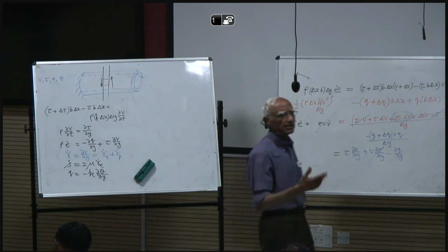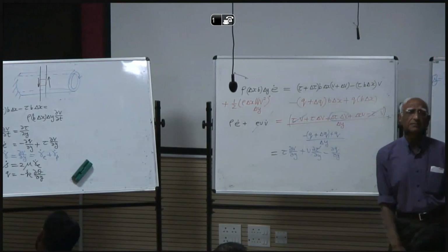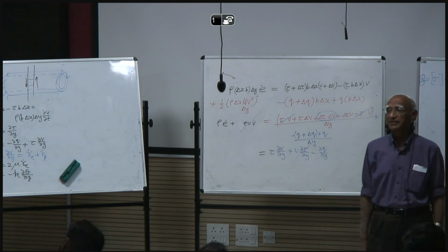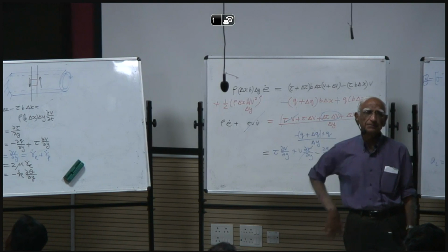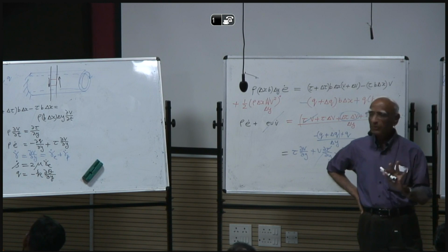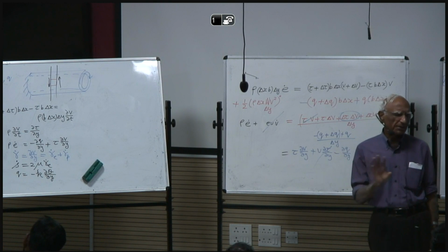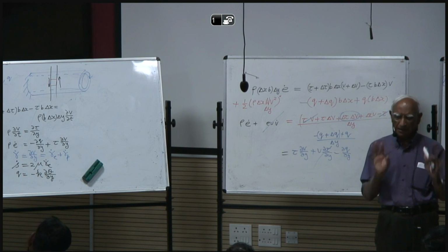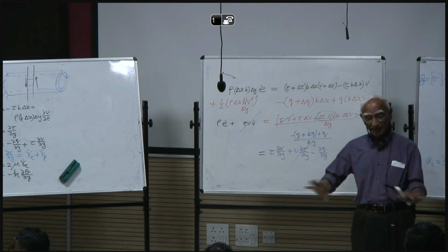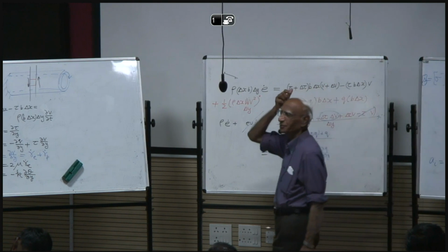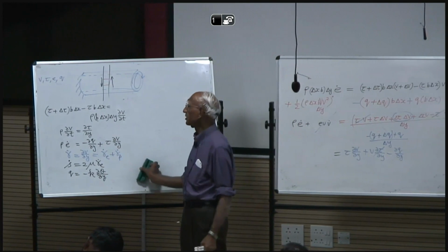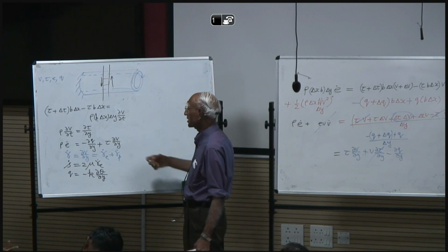You can have K depending upon temperature, or you can have K constant, or you can have K depending upon plastic strains. I mean, it's possible, but theory doesn't rule it out. The thermal conductivity can be constant, can be temperature dependent, can be strain dependent, can be strain rate dependent. Don't ask me what the expressions are, but in principle, yes, you need to do experiments to figure it out. But still we have a problem, because we don't know what gamma p dot is.